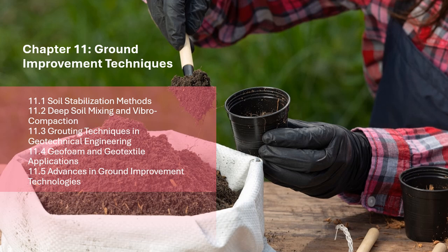1.3.3.2 Groundwater Control and Seepage Prevention. Grouting is often employed in areas with high groundwater levels or water-sensitive soils. It is used to prevent water seepage into excavations, tunnels, or basements, and to create impermeable barriers in dams, levees, or tunnels. Chemical grouting and permeation grouting are commonly used to reduce permeability and control groundwater flow.